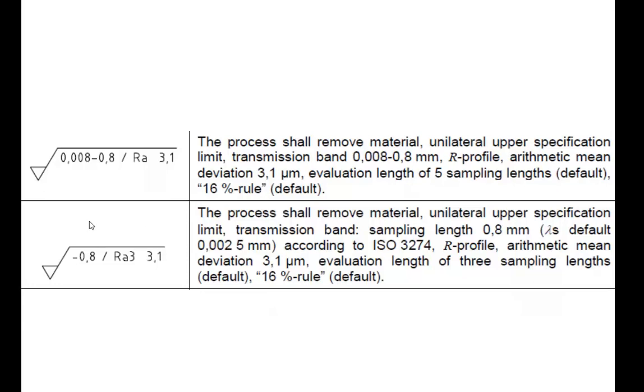Totally, this means along three paths, make the measurement and determine the roughness value. If all three measured values are below the limit, at maximum equal to the indicated roughness value on the technical drawing, then say that the surface is good enough in its pattern, in its quality.